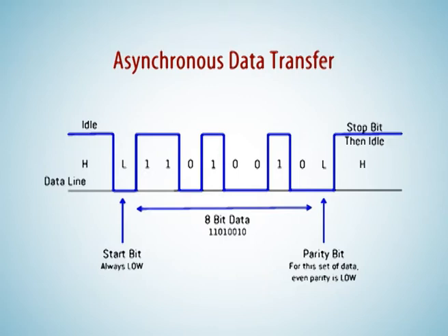To synchronize receiving of a group, the data stream is preceded by a start signal and followed by a stop signal. The start signal prepares the receiver clock for arrival of data, and the stop signal resets its state to enable triggering of a new sequence.